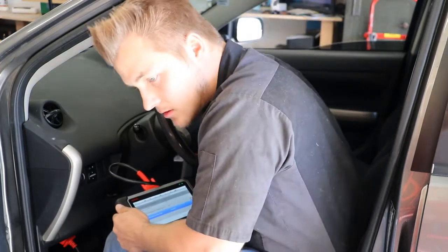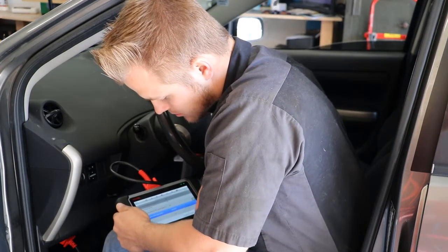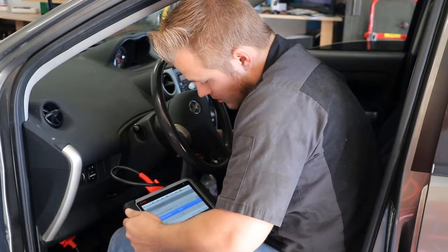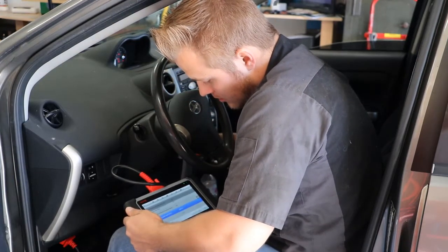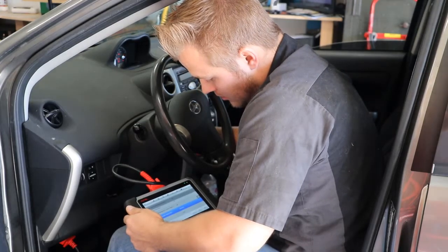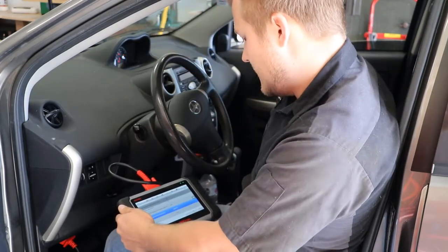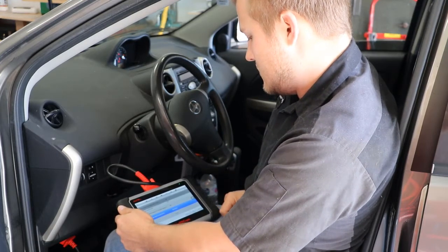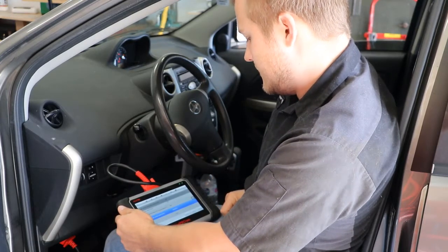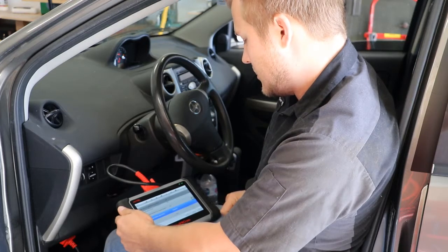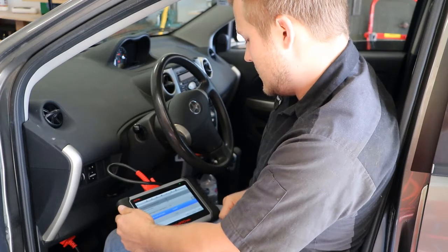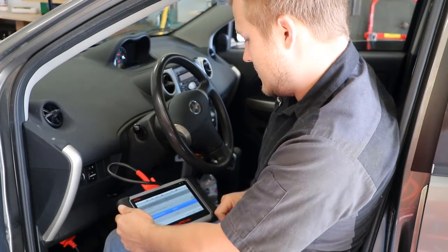Alright guys, at this point what I'm listening for is the click or the tick sound from the engine bay for the computer sending the electrical signal to activate the solenoid, the purge valve, and I don't hear it. So I decide to start the car, and as the car's running, I'm changing the on and off to see if there's any change in the RPMs, which there should be. There should be some type of stutter or change after the engine is warmed up and settled down. And after a bit, this is what we got.